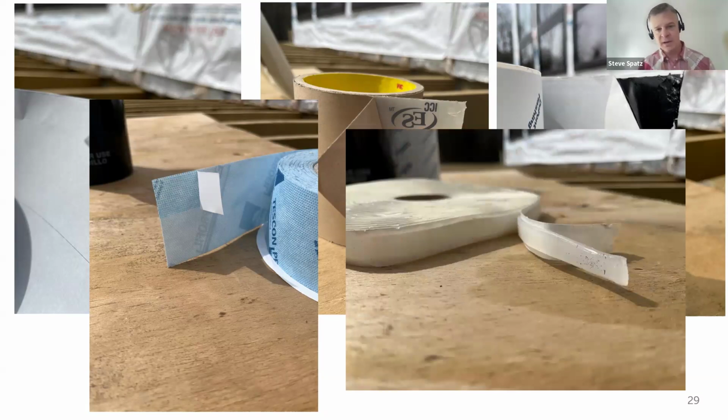And then also gaskets that are the same type of pressure sensitive product, but without a backing to them. These sorts of gaskets can be used at the termination of the bottom of a wall where you're sheathing an exterior wall, overhanging that sheathing the height of the band joist of the floor system it's going to be installed on. And rather than trying to tape that sheathing to band joist to foundation joint, this type of gasket can be put along the bottom of the band joist at the exterior before the sheathing is attached and create an airtight barrier there.